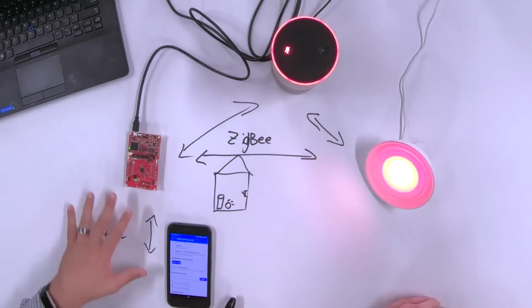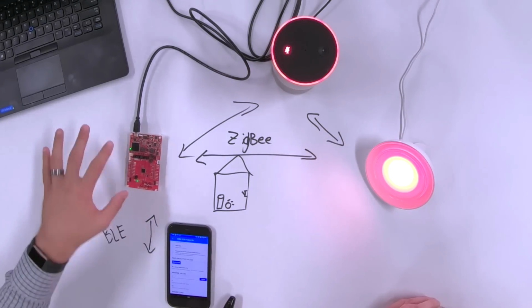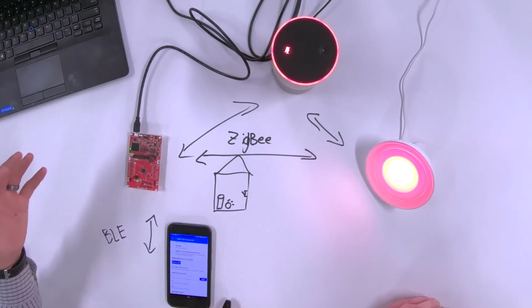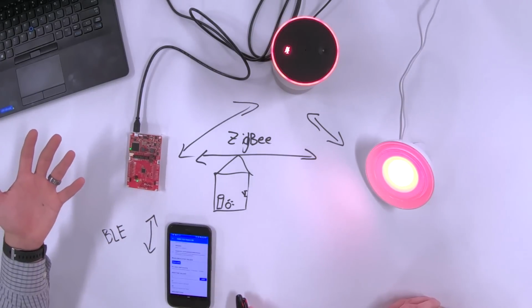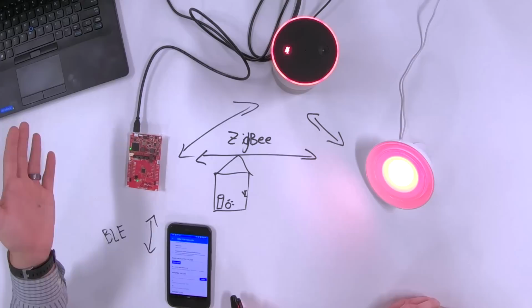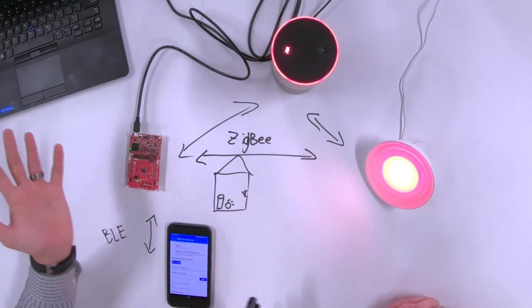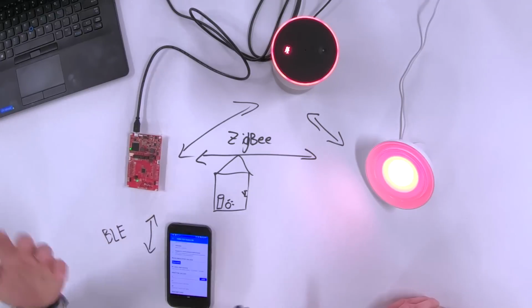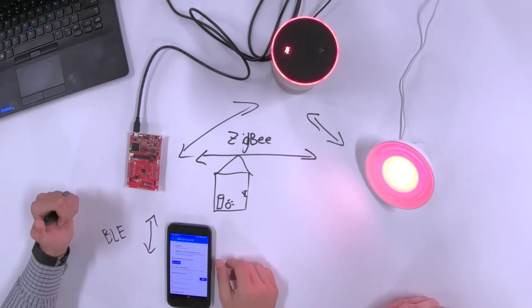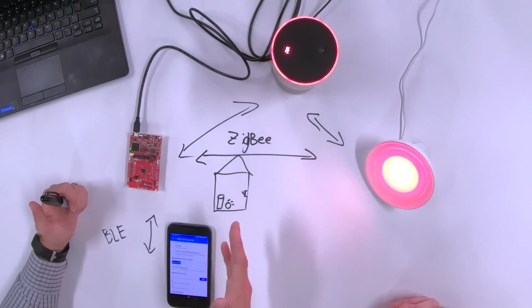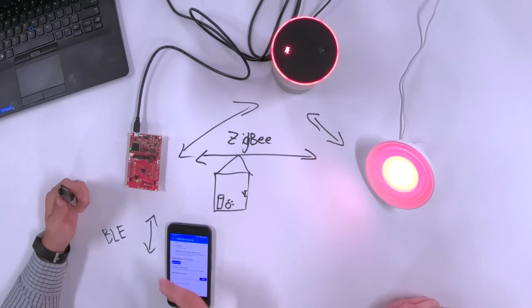Yeah, I'm writing to a BLE characteristic on the BLE stack side of things. And then the DMM module is then, we know we're looking for this value, so we send that to the Zigbee stack. The Zigbee stack will then do nothing to do with DMM, it just does Zigbee operations, right? So it'll send that Zigbee command to its parent, whoever it is on the mesh network, and that will eventually route itself to the light that we have bound to.